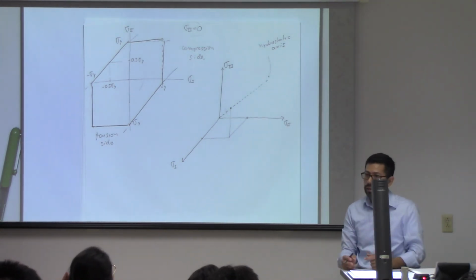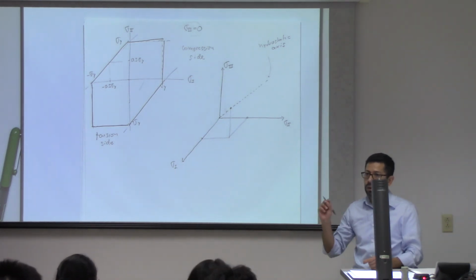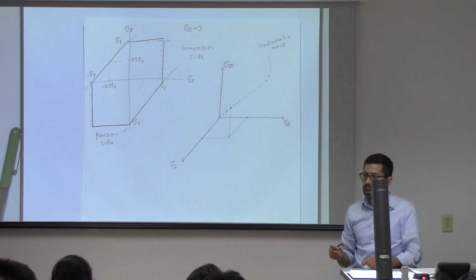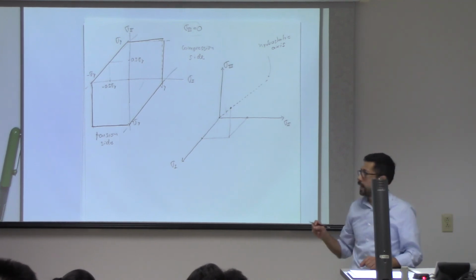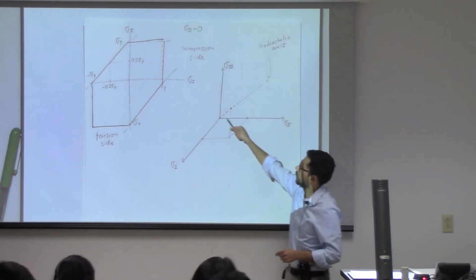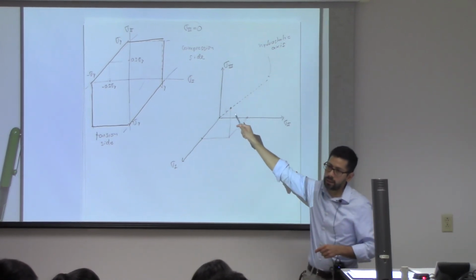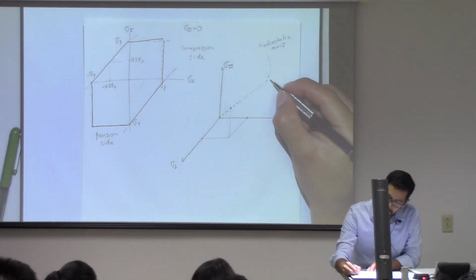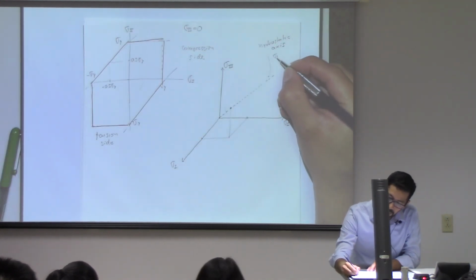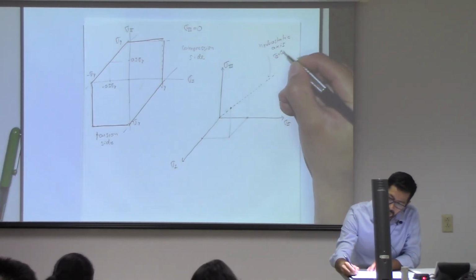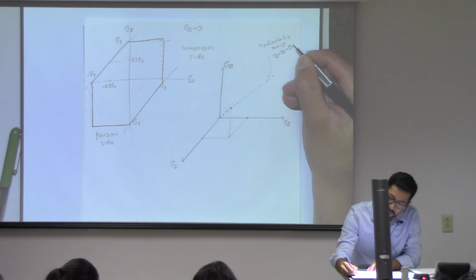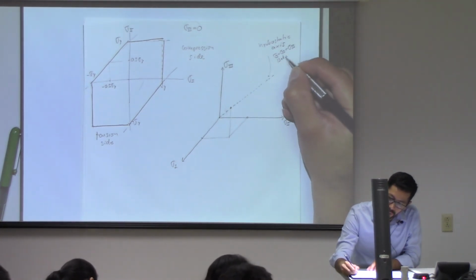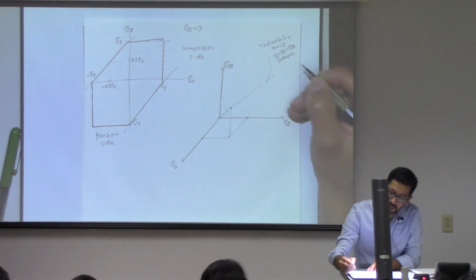In that axis, always all your principal stresses are the same. So that's the line also where if you have an isotropic state of stress, it will plot always in that line. So in the hydrostatic axis, sigma 1 is equal to sigma 2 is equal to sigma 3, isotropic state of stress.